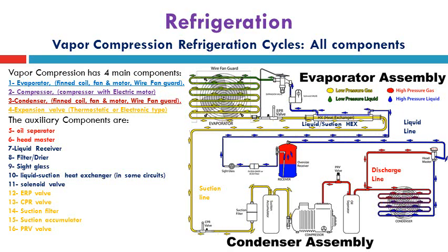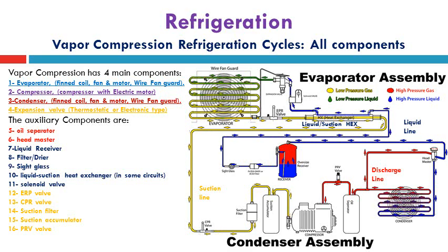The crankcase pressure regulator valve is also connected, but near the compressor outside the cycle, to control the crankcase pressure based on the compressor performance, to protect the compressor from working outside its design range and to save its lifetime.